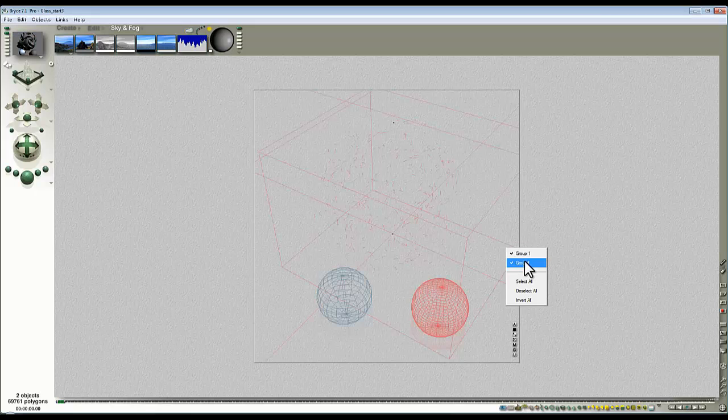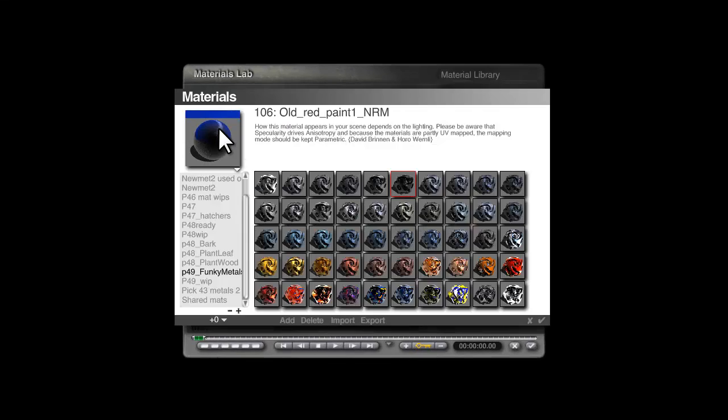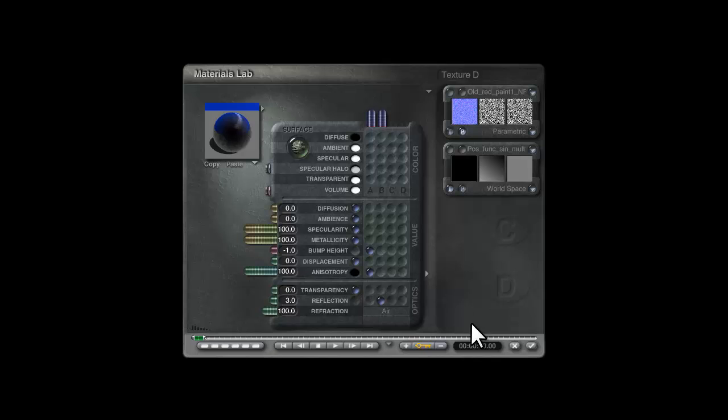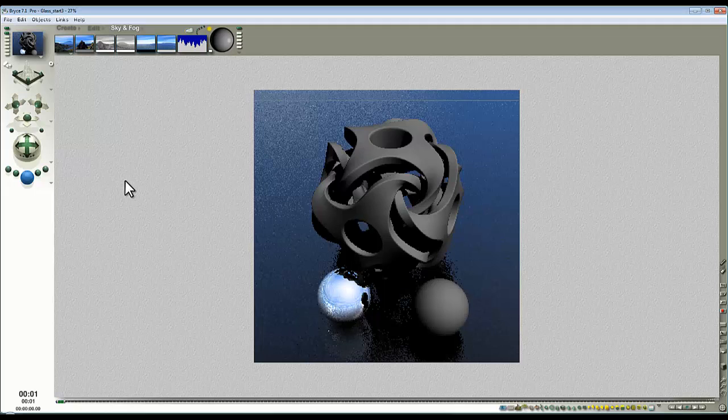What I'm going to do is modify the ground plane to start with, and give it one of the very dark versions of this material. It uses this anisotropic effect, what we know about metallicity, and an extreme form of reflection used by out of range functions, and that creates this sort of effect on the ground. The important bit about this choice was that it doesn't have any diffuse response to talk of, so we don't have the problem with the shadows that we had in the last video.